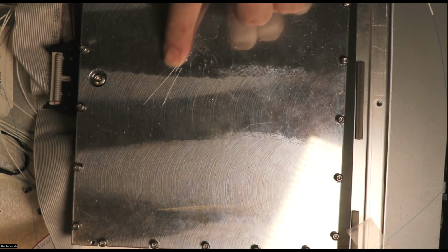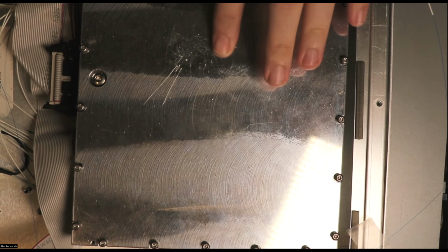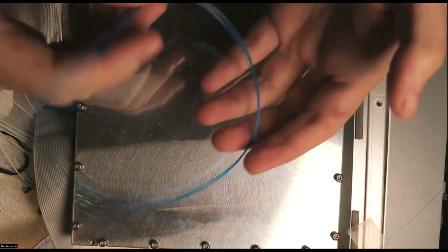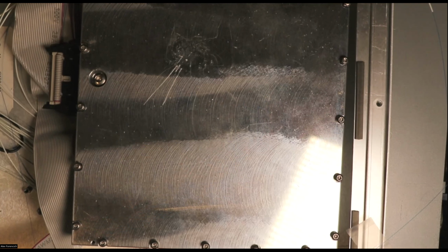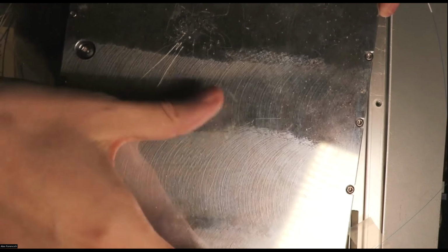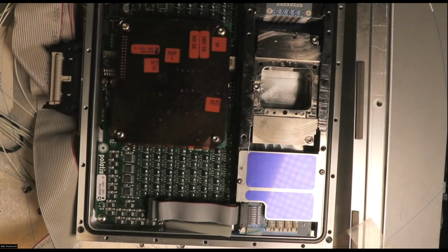It was outfitted, or at least it seemed like at some point it was outfitted, with a bunch of temperature sensors, but it was never fully assembled. So there's nothing connected up to the LC connectors on the output, and everything coming off of the switch is just bare pigtail fiber. Originally I was thinking, maybe we just need to terminate all the fibers and then it'll work. But it seems like the switch itself needs to be calibrated or something. So in the process of trying to figure out how to do that, I opened up the actual switch module.